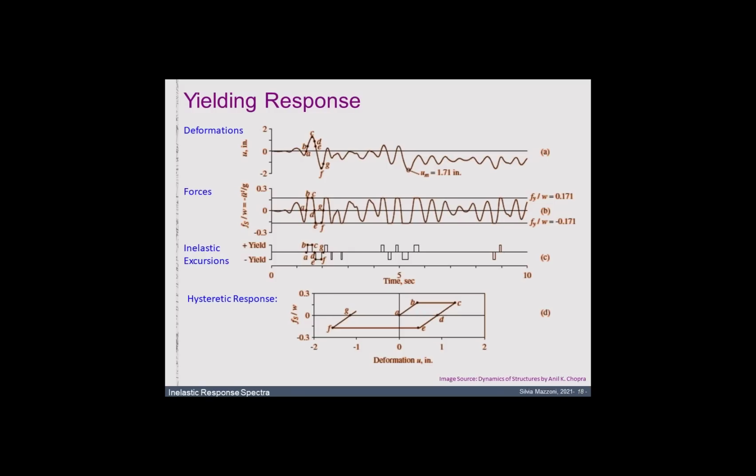This is actually a great resource to start looking at inelastic response. On the top, you see the forces. In an elastoperfectly plastic system, the deformation is at the top. In the middle, we look at forces, and the forces pretty much cap at the yield strength.